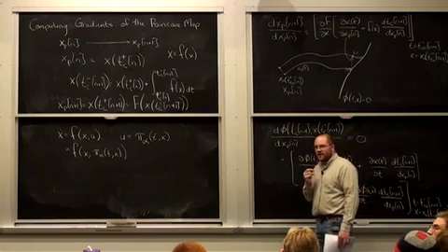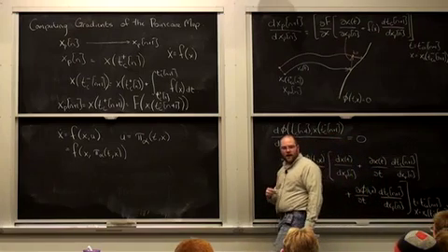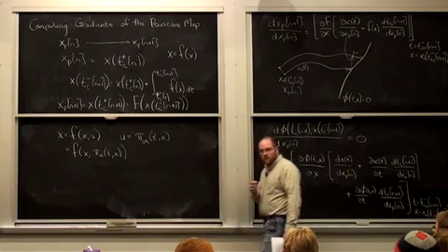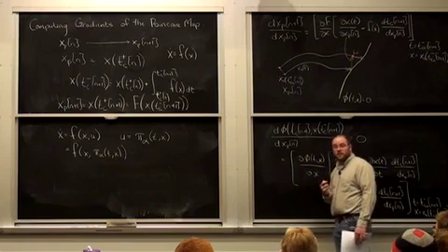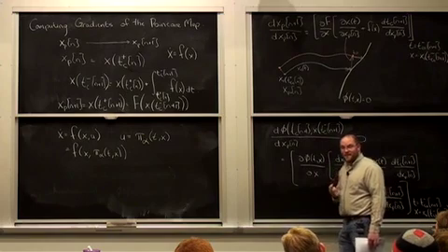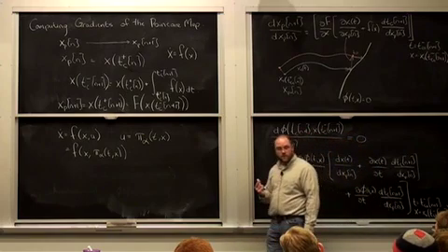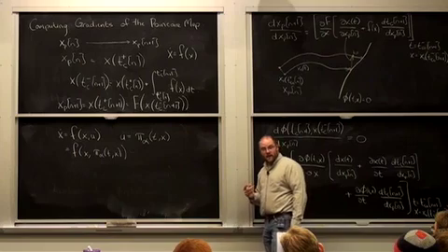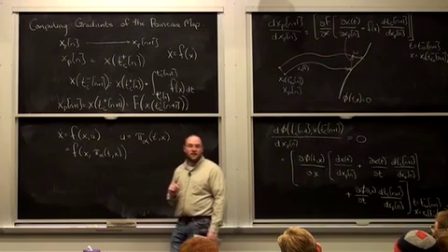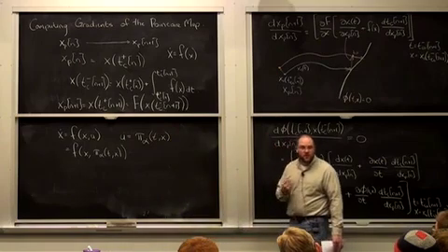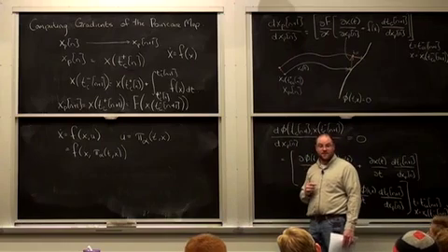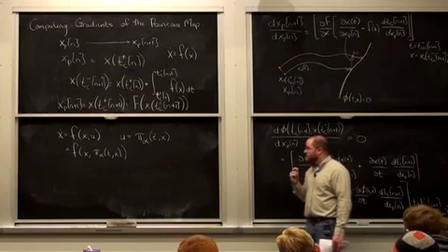Fumia's got a compass gait that works with open loop trajectories that play out, where his major parameters are the frequency and phase of the periodic input. It's amazingly stable coming out. It's like a beautiful example of open loop stability. So Fumia and I have been talking about changing the parameters of his open loop controller once per step in order to try to regulate the behavior of the system. There's lots of ways you could do it.